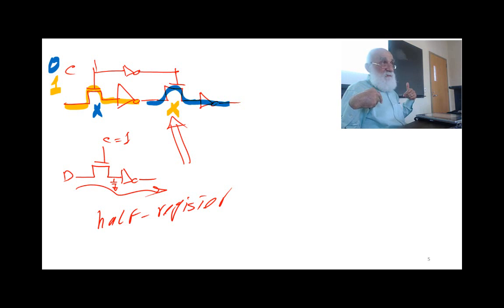The beauty of this is it only uses 6 transistors, but then there are other structures that use the same thing. There are other structures with few transistors as well. Then there are other CMOS structures, but I just wanted to show you that not all master-slave flip-flops are necessarily built by those cross-coupled structures. Okay, but when you do edge trigger, you really have no choice but to go to that big hardware, that structure there.